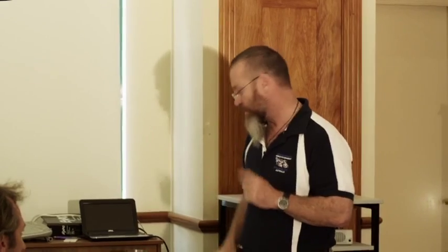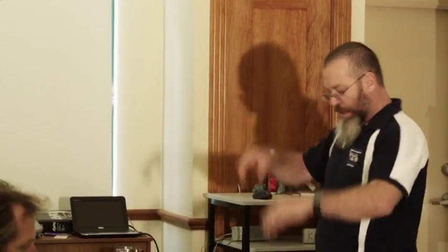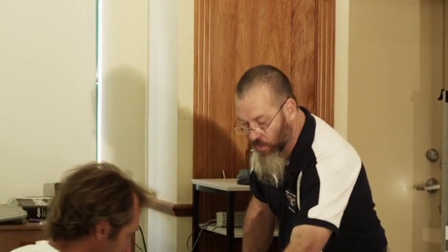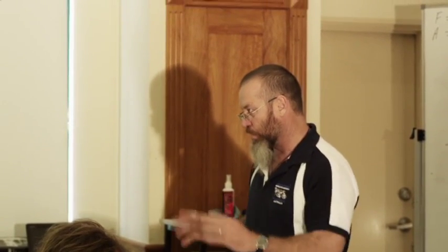I put it to you. Consider it. You have been told. Or the alternative is a type D connection on page 191, 189 on the old book, which is a cast-in rod, which is what you guys are doing in Cairns all the time. And that's the reason they do this. That's why they go to all this trouble of putting a cast-in rod in there, because A, it's cheaper than using a ChemSet, and B, it actually works. It can work inside all these parameters and tolerances.